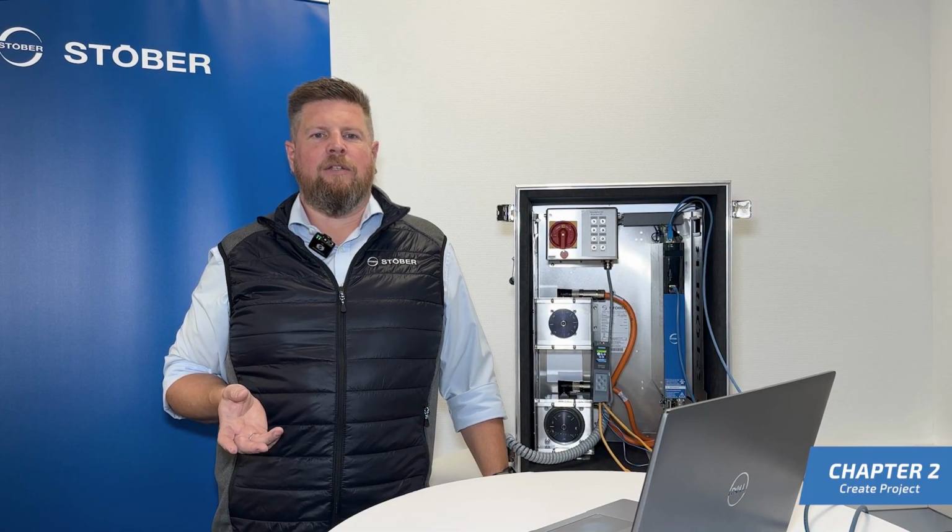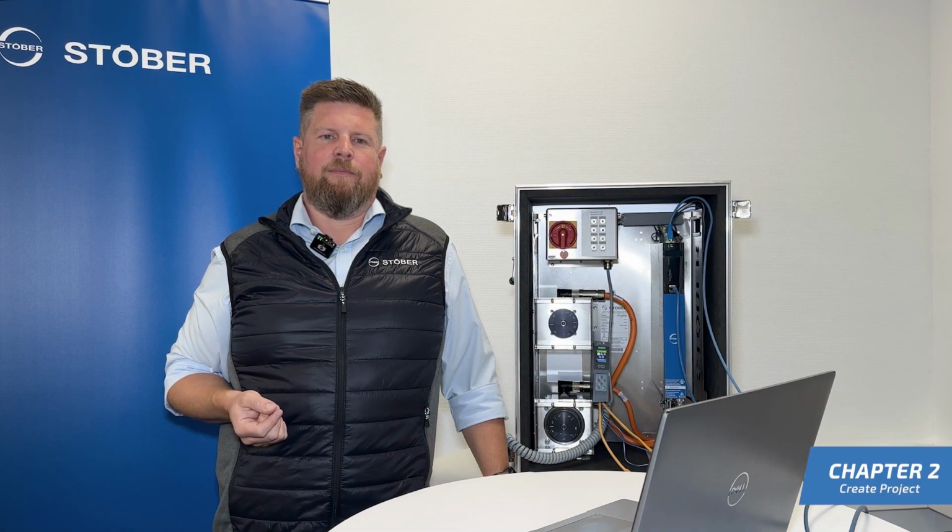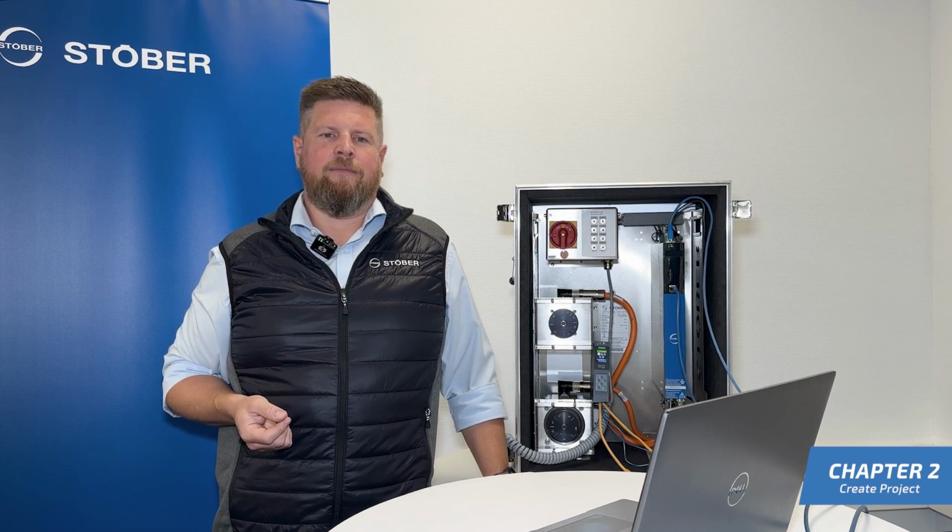Axis B I set to ProfiDrive with the lean motor, even though it is not being used. Next, I set the power supply to 230 volts, activated the one cable solution option for the encoder, and limited speed, acceleration, jerk, and quick stop deceleration to suit the application. I set the reference speed to 3000 RPM. Then I transferred the configuration to the drive controller, saved the values, and restarted the controller.